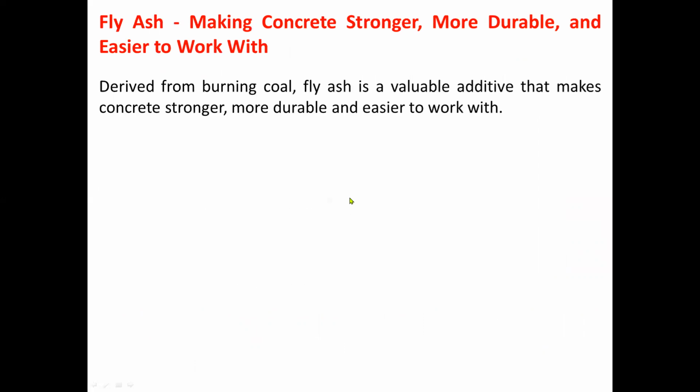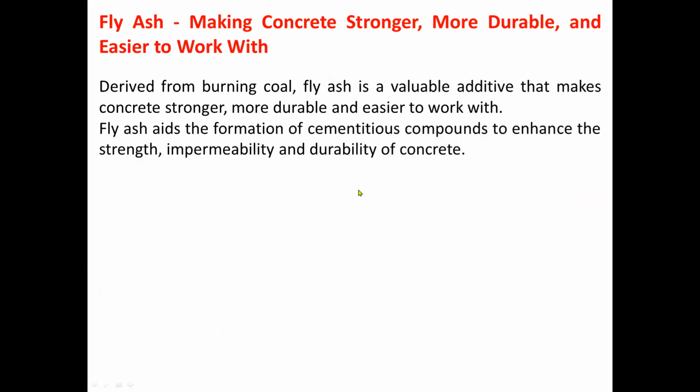Fly ash, making concrete stronger, more durable, and easier to work with. That is fly ash. It is derived from burning coal, and fly ash is a valuable additive that makes concrete stronger, more durable, and easier to work with. Fly ash aids the formation of cementitious compounds to enhance the strength, impermeability, and durability of concrete.